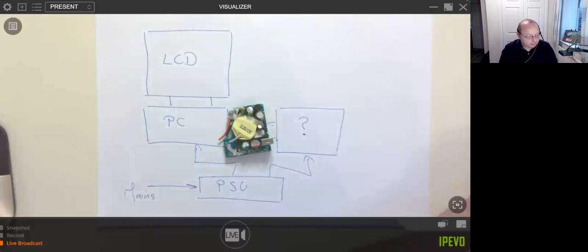Let's say, for example, the diathermy product I worked on many years ago. The power for the diathermy was all digitally controlled. So what if the cable half fell out? It would probably get a rather sorry looking signal. The way we dealt with that, if it got something that looked like a sorry signal that was going to cause a dangerous situation, is you've got to design the electronics such that it can handle that and make it safe.